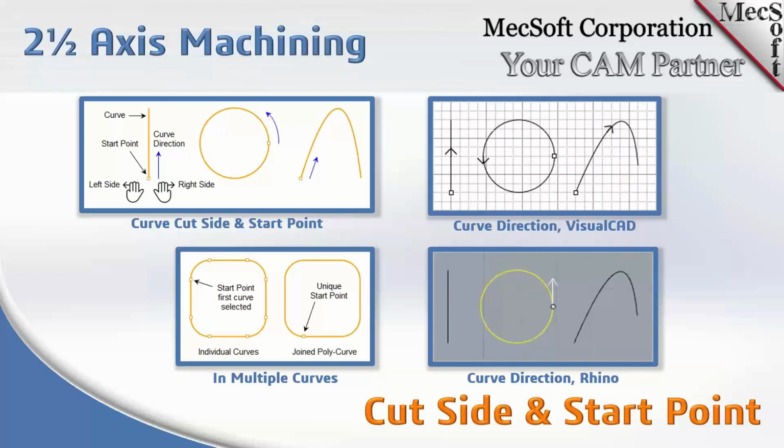So that is the method you really want to strive for if you're going to do any curve machining. Obviously it's more than one curve, so always remember to join your curves or merge them together. And then on the right, we just see the different indicators of the start points and directions of curves. So basically, understand here in profiling, the tool is going to start at the start of the curve.